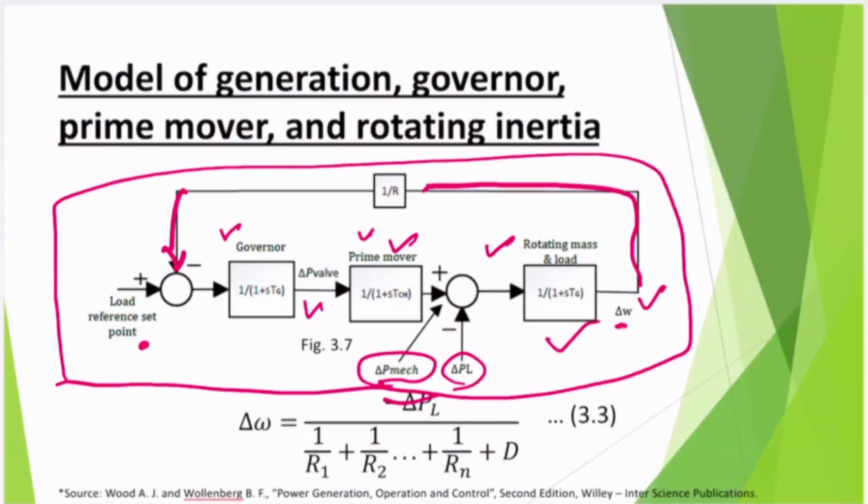Every second the frequency keeps on oscillating, the valve keeps on changing its injection, and the prime mover keeps on moving in a different way. Hence we always try to reduce the gap of delta omega. So the delta omega is expected to be 0 in practical circumstances, where we achieve the desired frequency by managing all these changes.